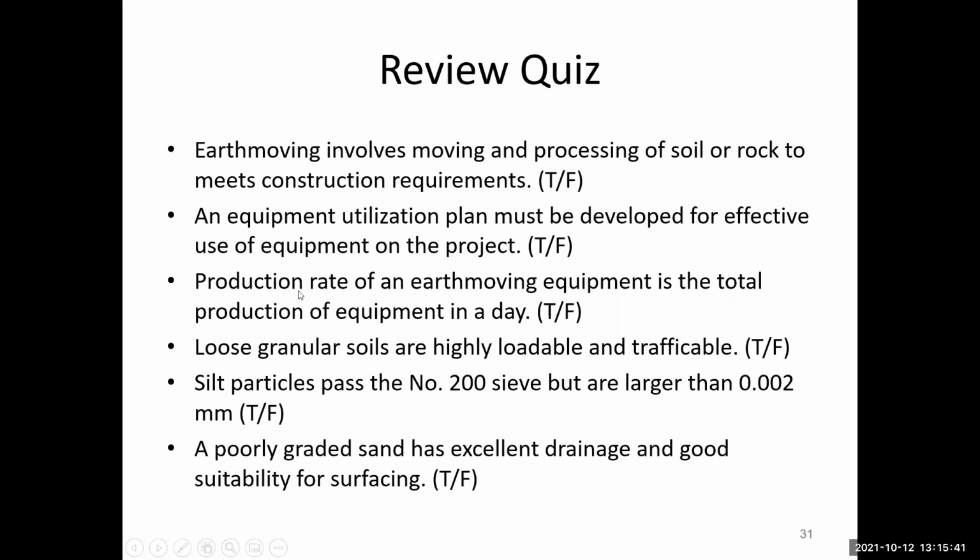Production rate of an earth moving equipment is the total production of the equipment in a day. Loose granular soils are highly loadable and trafficable. And silt particles pass the number 200 sieve but are larger than 0.002 millimeter. True or false? And poorly graded sand has excellent drainage and good suitability for surface. I think you should review this topic and then you can find the answers to these quizzes.